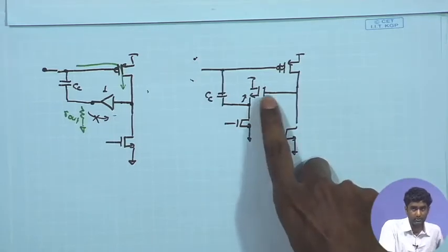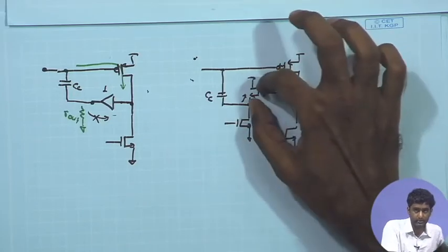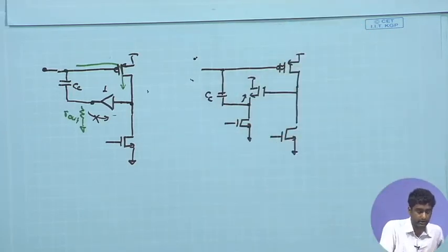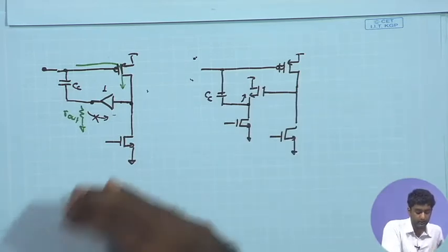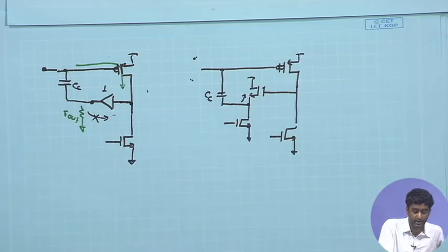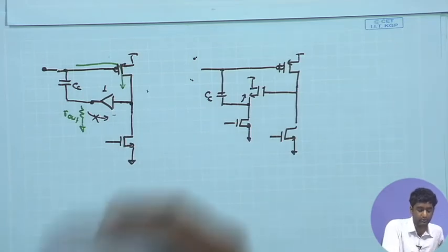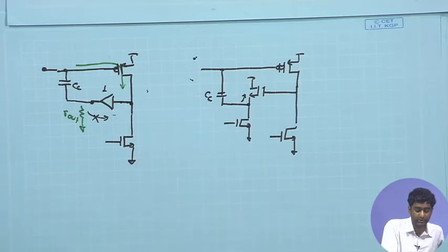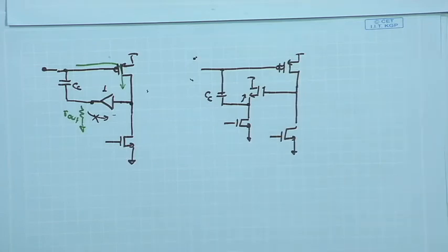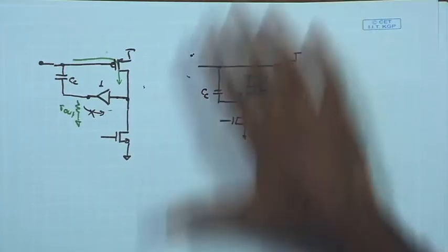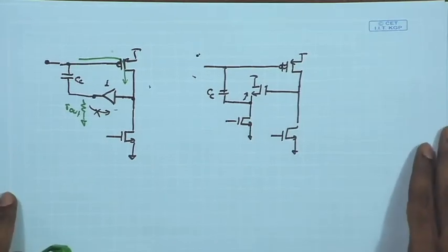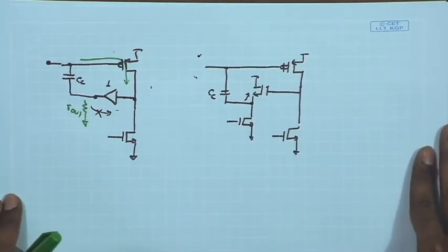So, that is another option, but that also has its limit, because ultimately you will end up increasing the area of this MOSFET, and as a result the channel area will increase. Apart from the power, we also have a severe constraint on area in this particular application, because we are going to have many such channels catering to different electrodes, and we do not want to make any of the components too large to meet our design specification. So, both from the point of view of power as well as area, having this particular scheme can create issues. It can violate our area constraint per channel or power constraint per channel.